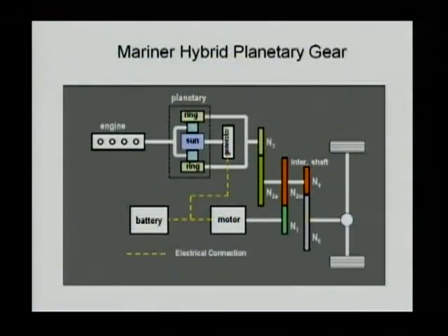On the other hand, we know that on a planetary gear system, all three gears, all three outputs, need to be connected to something. Otherwise, if one is freewheeling, the system is not able to transfer torque. So in this case, the ring gear has to be connected to something, otherwise the way we just explained will not work. So we need to introduce another set of gears that connects the ring gear to the final drive. If you look carefully, the ring gear is now connected to N2, and N2 is driving N2E. N2E is mechanically linked to N2M and N4, so they're on the same shaft.